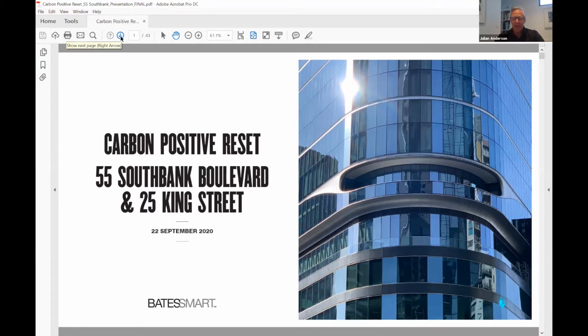So the predominant material in the extension is cross-laminated timber, but we do also use glue-laminated timber, where layers of timber are cut in the same grain and jointed and glued together. This gives the glulam product strength in a direction, and it's for this reason that glulam is predominantly used for beams and columns.